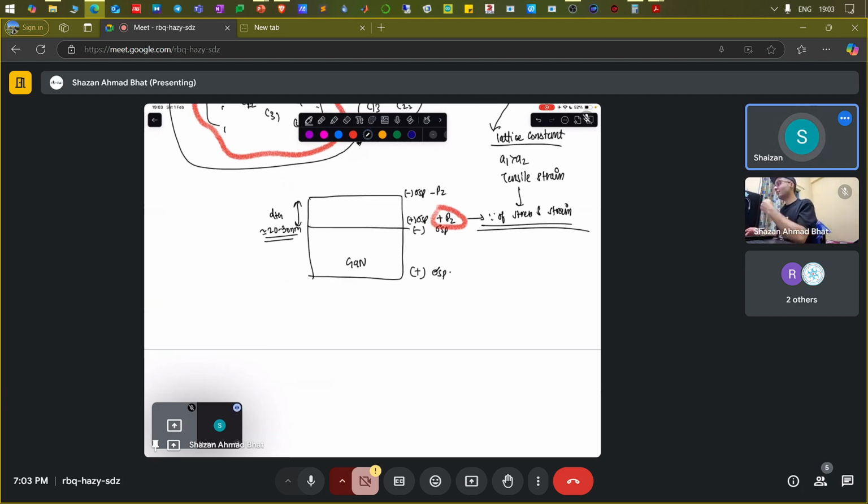Because there is a tensile strain because of lattice mismatch, that's why these components come. If you do something, maybe interface engineering or band engineering or thin film engineering, where you can make it absolutely relaxed over the gallium nitride, you can totally omit these piezoelectric components. But these are still there in most of the AlGaN which is grown over the gallium nitride. So these components come because of the piezoelectric stresses and the piezoelectric strains.